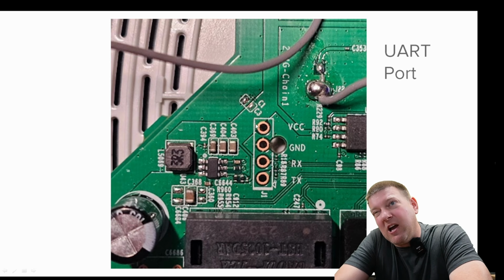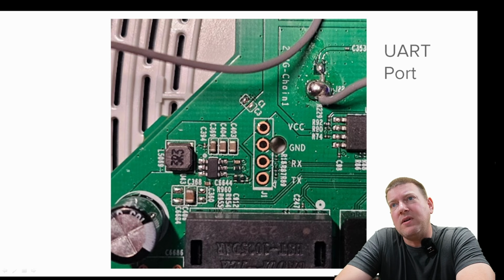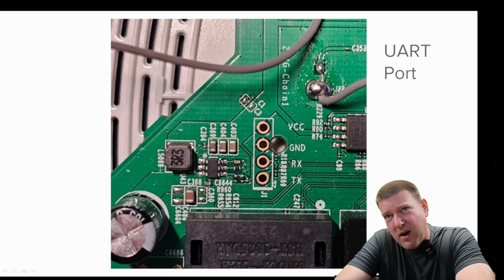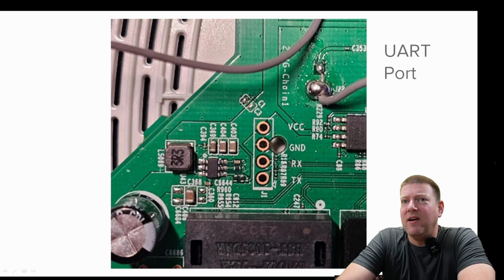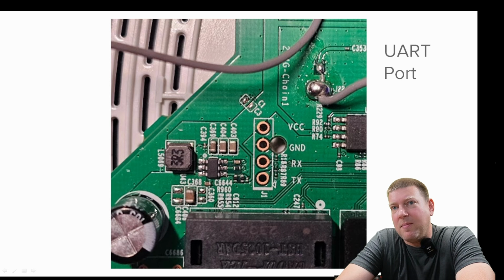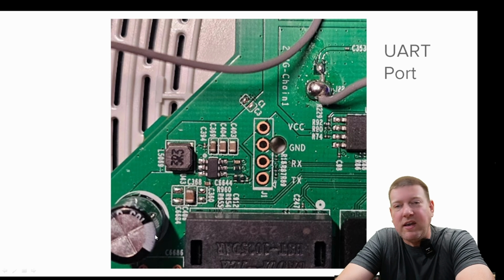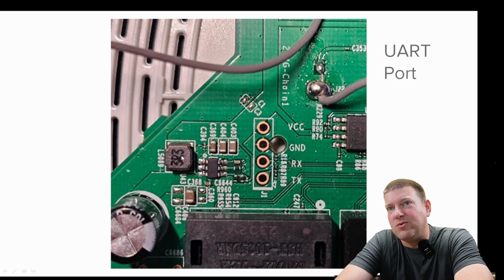And since it's on UART, I would assume that that is what, a 5-volt rail, I guess. And it only makes sense also because look right here. Here is your capacitor. And notice this side right here, your electrolytic, it's white. That means that you're negative. This over here is your positive, and it goes right here to that inductor and that controller.